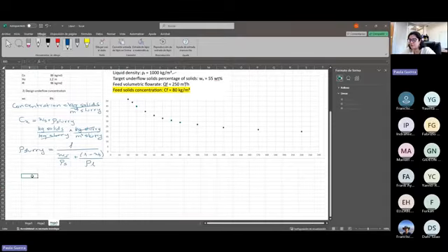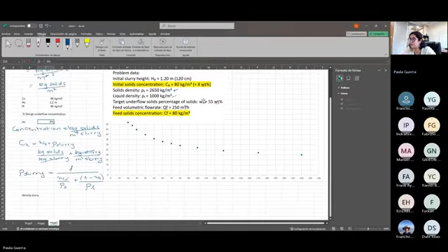Okay, so let's start here. This would be first the density of the slurry. This is going to equal 1 over, oh, I'm sorry, made a mistake here. This is the design underflow concentration, so this would be 55%, not 8%. 8% is the feed solids percentage, but what we desire at the underflow is 55.